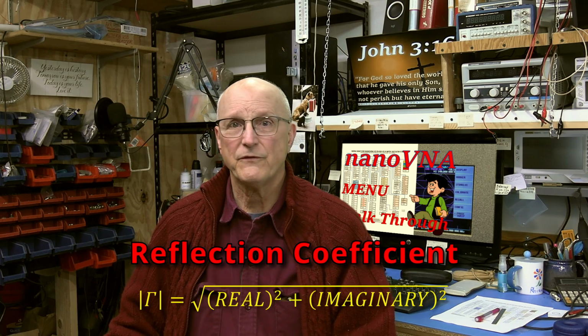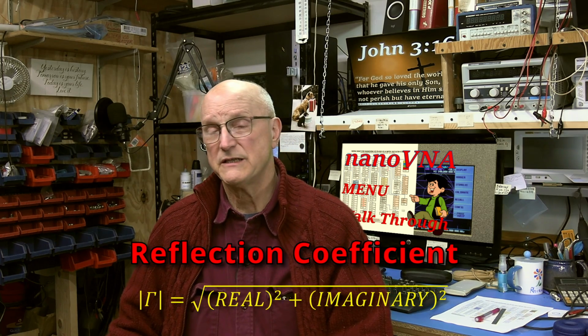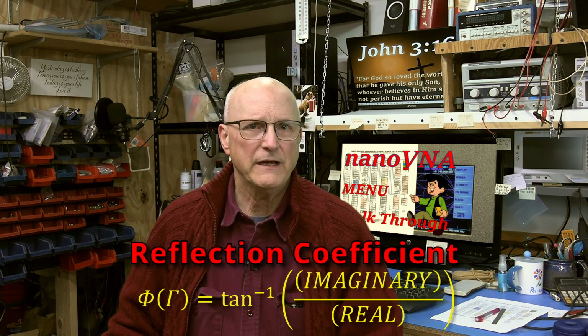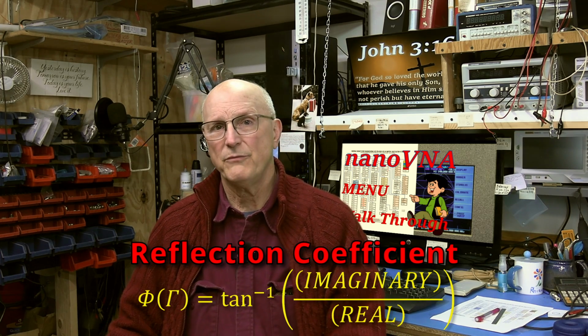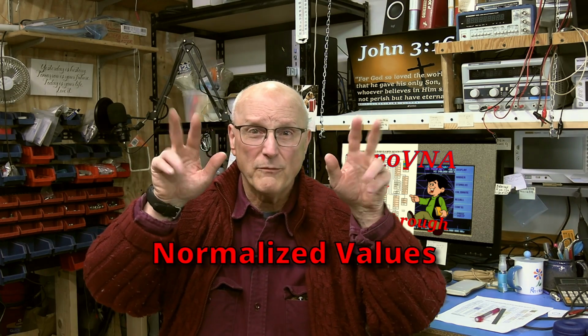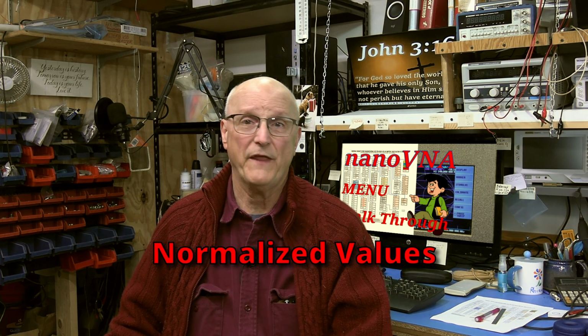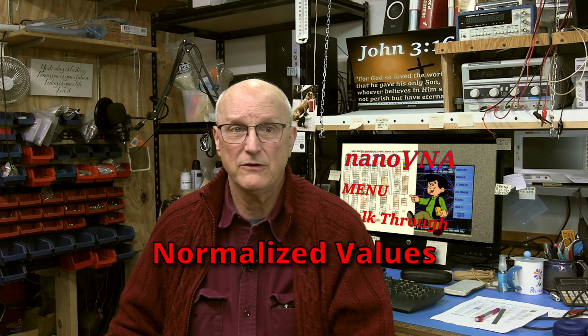The magnitude of the reflection coefficient is found by the square root of the real part squared plus the imaginary part squared. The phase of the reflection coefficient is found by the inverse tangent of the imaginary part divided by the real part. I've provided a go along with the video sheet with all of the equations for you. You'll find a link to this downloadable sheet in the description. Another thing that you're going to be hearing a lot about is normalized values. It is a way of measuring one thing relative to another without regard to an absolute value of either thing.